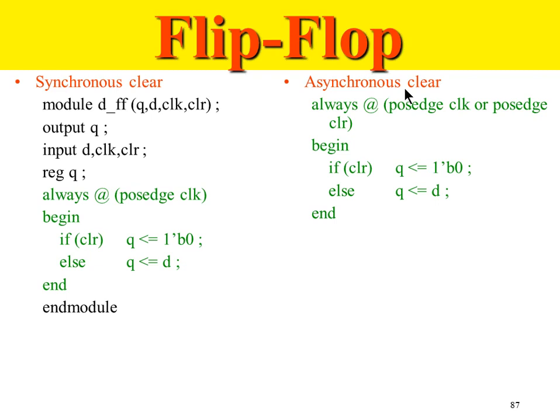So anything with respect to clock, everything is synchronous. Anytime it is not dependent only on clock, it can be asynchronous logic. And wherever possible, you should avoid developing asynchronous logic. You should use synchronous everywhere. Even clear, which is a reset signal, has to be synchronous wherever possible.